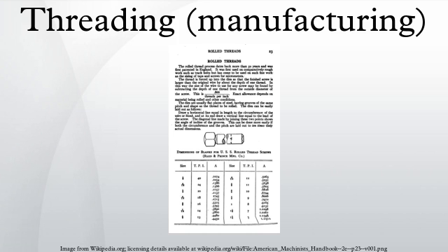This type is more common than the former, but is limited by not being able to form the last 1.5 to 2 threads against shoulders. Planetary dies are used to mass-produce threads up to 1 in diameter. Thread forming is performed using a fluteless tap, or roll tap, which closely resembles a cutting tap without the flutes.